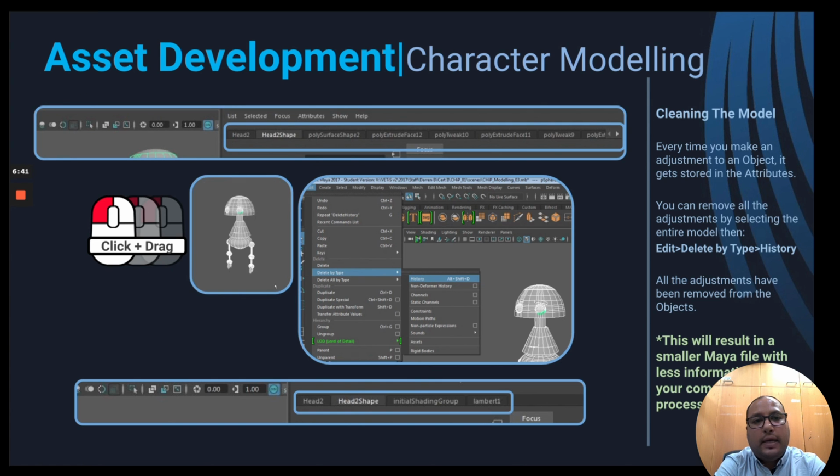Cleaning the model. Every time you make an adjustment to an object, it gets stored in the attributes. You can remove all the adjustments by selecting the entire model, then Edit, Delete by Type History. All the adjustments have been removed from the objects.